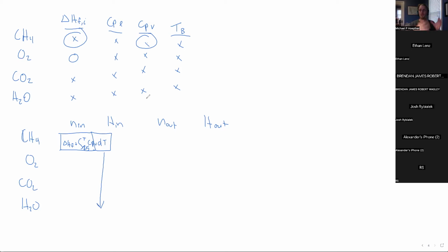So then the only difference between methane and water from a thermodynamic perspective is: is its heat of formation different? Is its heat capacity different? What's its boiling point? Right. So those are the only differences from a thermodynamic perspective of these different fluids to determine how much energy goes in and out of the process. So these methods, right, the system of thermodynamics uses confusing and archaic language, but the end result is a really algorithmic, sort of straightforward calculation.